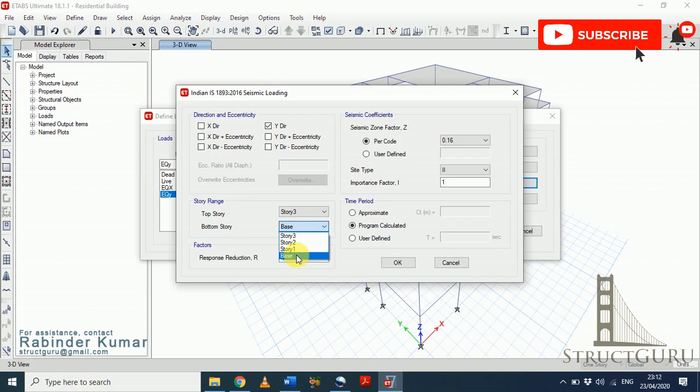I always choose from base to story 3. So for response reduction factor, as we saw from the code value, it was 3. So choose this value. Now what is the response reduction factor? Let me define it. It is the factor by which the actual base shear force is reduced. In simple words, it reduces the earthquake load which is encountered by the building by the factor we input in